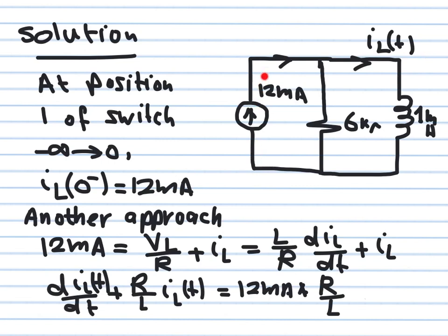So there was some transient behavior that happened at minus infinity, but now we are talking about from minus infinity to 0. Okay, and I am giving you a warning here. In the first stage, the switch was in its position from minus infinity to 0. But when I use my calculations, because the template we're using assumes 0 at the beginning, minus infinity here will be my 0 really. But when I move to the second stage, I will have to use the final value I reach here as the initial value for the second switch position. Let's see how this is going to work.